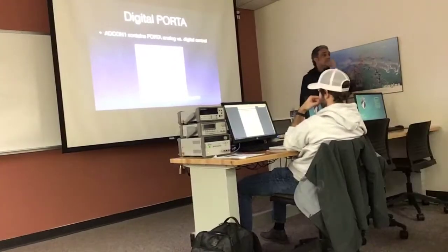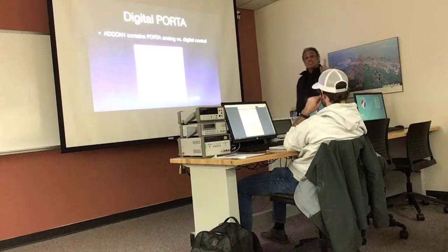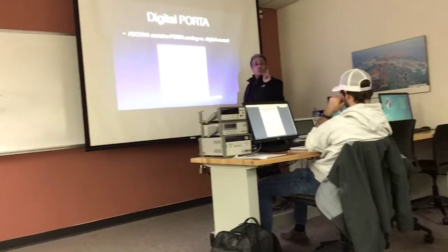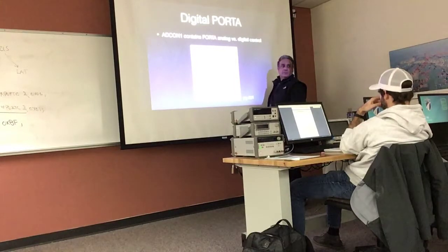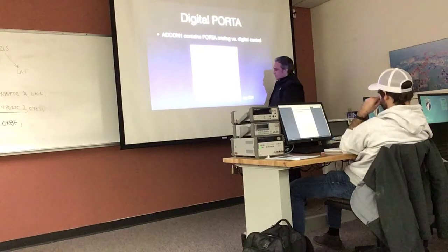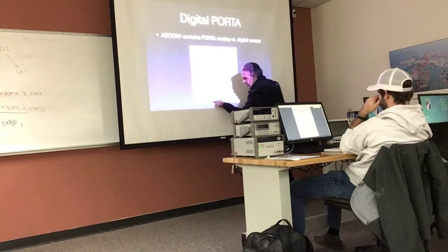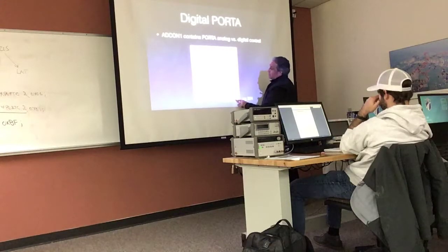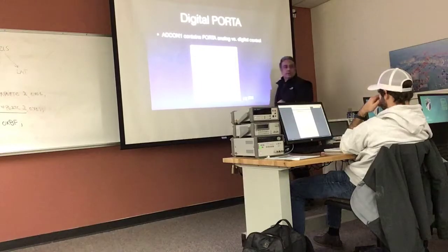See that? Here's the problem with this micro. This micro does not give you individual digital control. It is sequential digital control. So if I want A1 to be digital, you have to make 0 digital too. If I make 0 digital, you got to choose everybody else to be digital with it. There is no setup in which I can have 0 digital and everybody else analog.